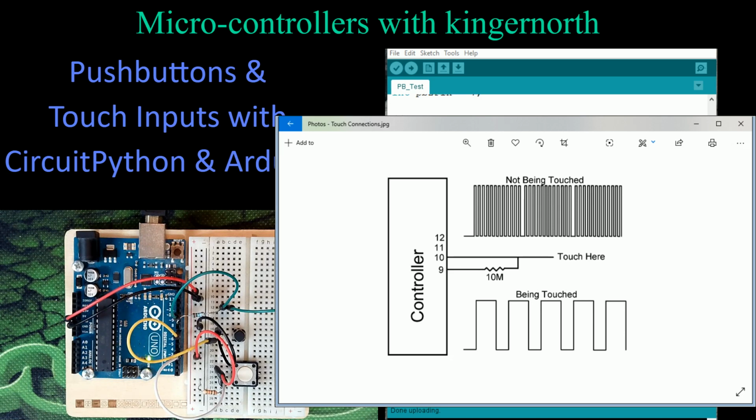During the long pause, it recalibrates itself, because capacitive touch is affected by humidity, temperature, a number of different things in the real world. Unfortunately, it's not always easy to understand, and there's a little bit of electronics here, but basically that's what happens, and it has to recalibrate itself. It's best if you let it recalibrate itself. So it reads this signal. When you touch it, where it says touch here, it's just a wire connection. On my board, it's just going to be an empty wire. And I'm going to actually take hold of it, and you'll see the light come on.